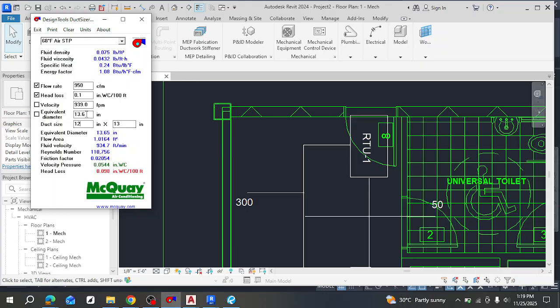So there's what they call static pressure. If the duct is very big, the air is not able to travel as far, but if it's smaller, it travels faster. If you're passing the same volume of air through a 12 by 12 duct and through a 16 by 16 duct, in the smaller duct the air tends to go farther. So that's why I round down instead of rounding up.